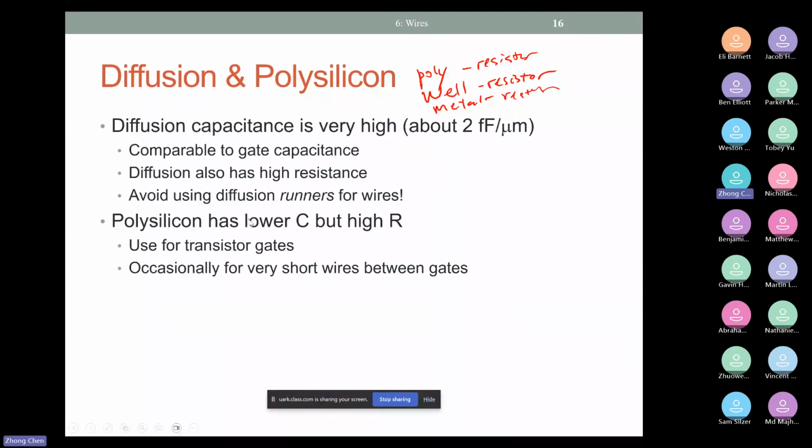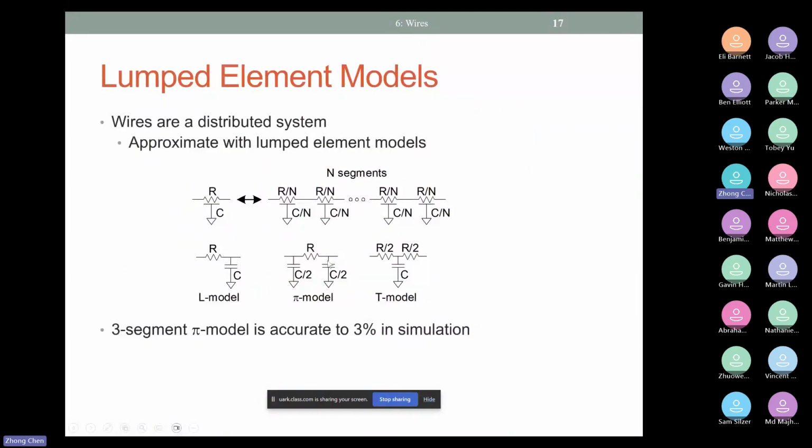So to give you some high-level understanding, this one is also very important. The question is, can I estimate my total resistance value and the total capacitance value if I run a piece of wire, for example 100 micron long with a width of 1 micron, for a metal two? If I have a piece of metal running like that, how can I build a good RC model?